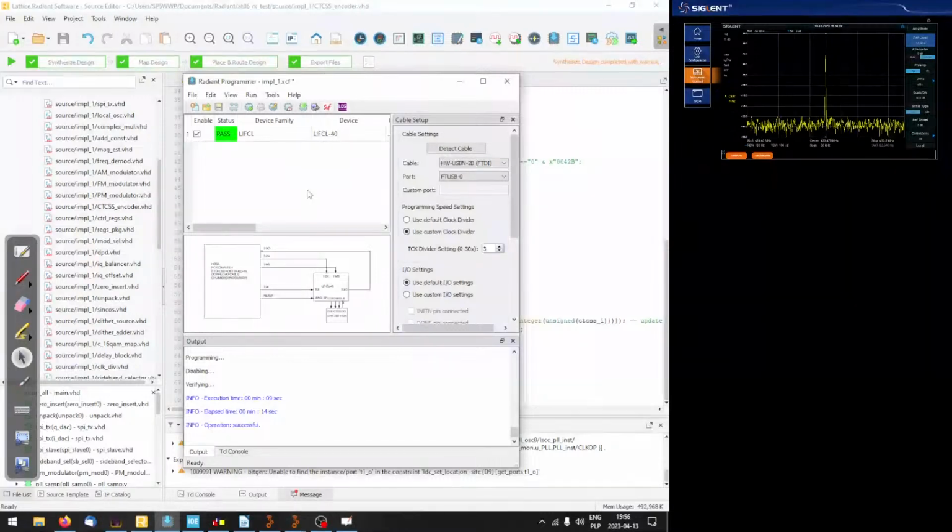All right, so right now it's set to 203.5 hertz. So if we set the register to 0, we shouldn't hear the beep. If we set it to 1, we shouldn't hear the beep either. But if we set it to 2, we should be hearing the 1 kilohertz tone. So I'm going to leave it just like it is. I'm going to put it just by the microphone.